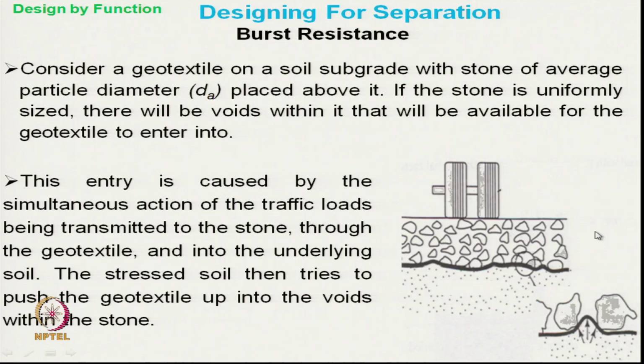So, this is the situation where for separation function the bursting strength is important. Here due to the load, the stones are pushed inside the soft subsoil, and depending on the arrangement of these stones, the subsoil will be pushed upward, where the geotextile is acting as separating agent for separation function.